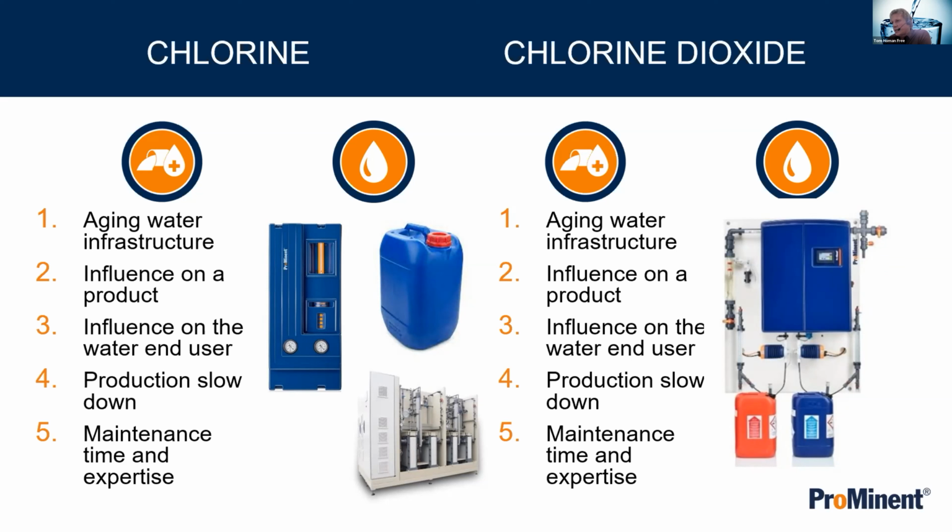from salt electrolysis. Chlorine gas is pure disinfectant, and it's cheap, it's readily available, but the handling of chlorine gas is very dangerous. You need trained operators, you need a big amount of safety measures. Chlorine dioxide, a little bit less, but there's two precursors that you need, hydrochloric acid and sodium chloride. Are those available? Can I store them? What are my restrictions on these? Pros and cons of chemical addition.